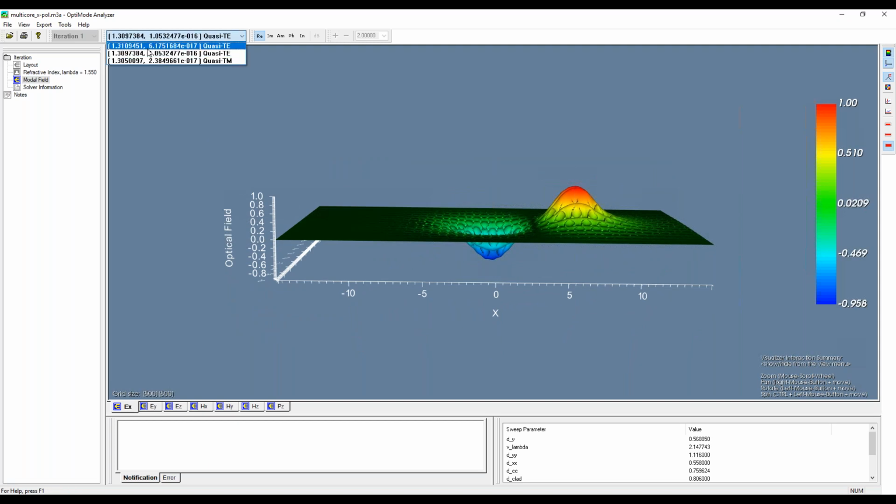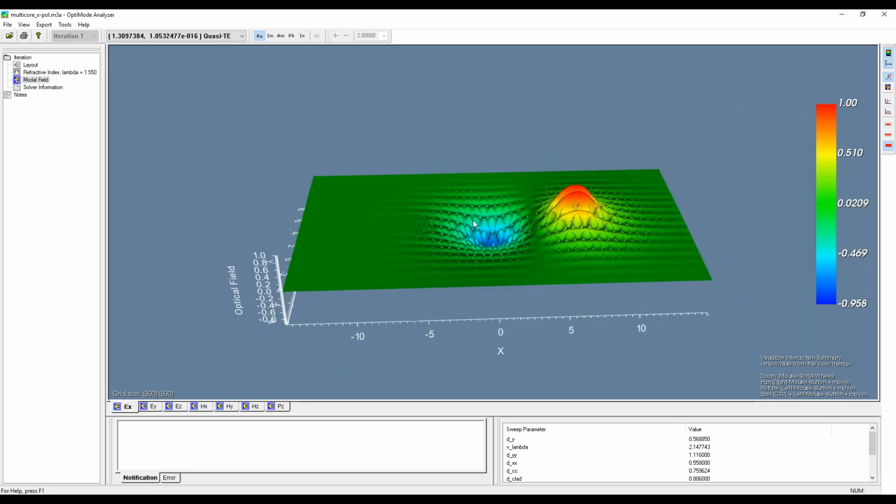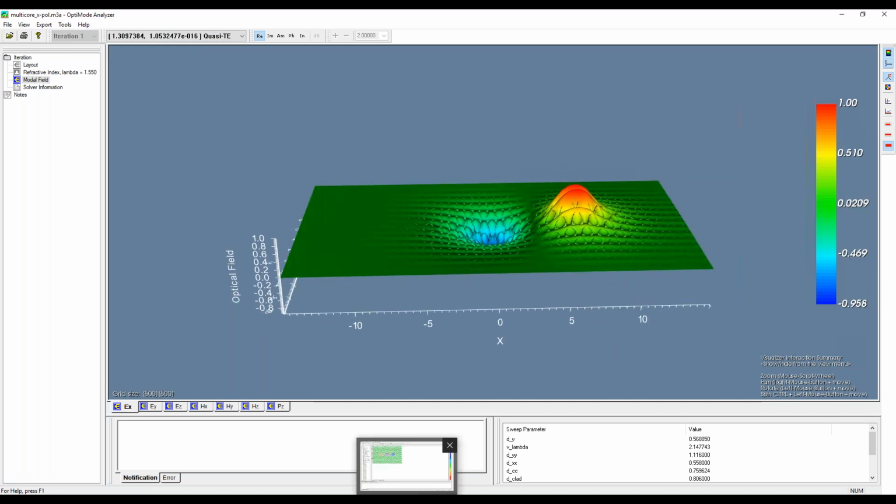And the difference between those, using that calculation I showed in the second or third slide, and using the wavelength, you can calculate the beating length, or the coupling length rather, and you get about the same answer as in the paper, about 620 microns. And all you have to do is calculate 2 modes. Now, if we go over to the other result,